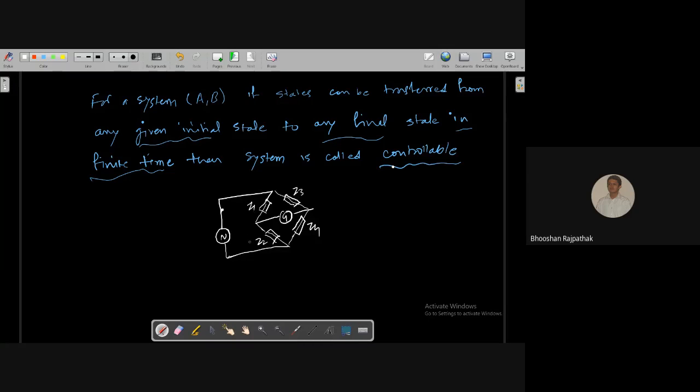All of you know this. This is a Wheatstone's bridge, where you have four impedances. In Wheatstone's bridge you have resistances, and one of them is unknown. And how do you find it? When the bridge is balanced, then you have Z1 by Z2 equal to Z3 by Z4. That is how you get the balance with Wheatstone's bridge.